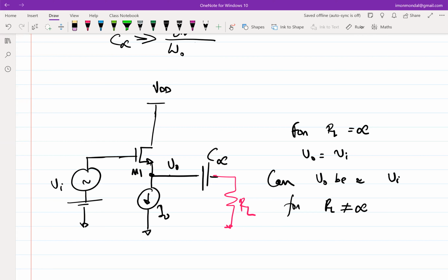Output resistance. Remember that first or second assignment, a box, whether it acts as a voltage source, whether it acts as a current source. So essentially whether RL is loading your circuit. If RL is not loading, your answer will be the same as RL equal to infinity. If RL is loading, then it will be something different. So what is the incremental output impedance, or rather, what is the impedance looking in?